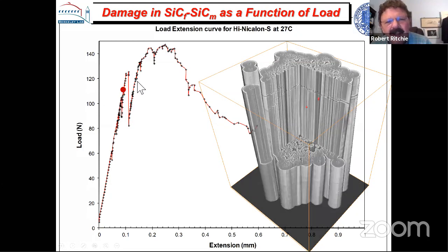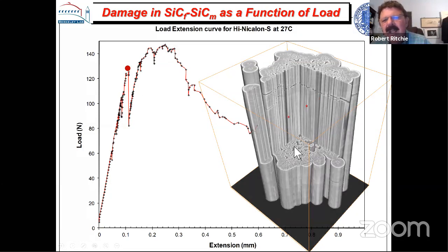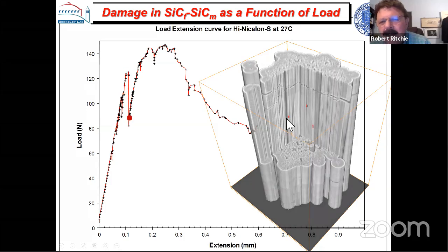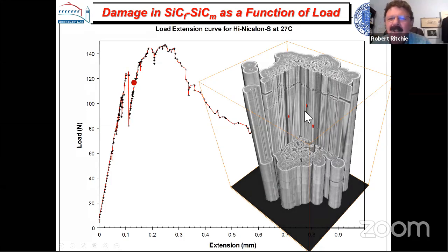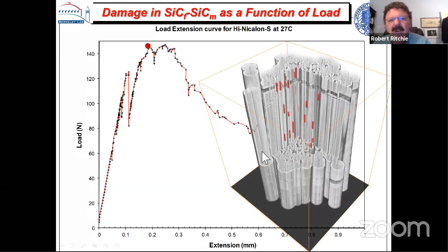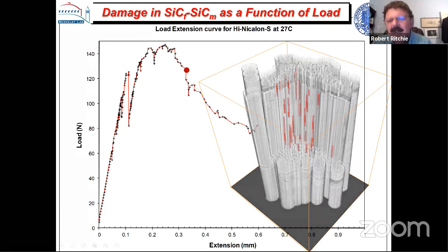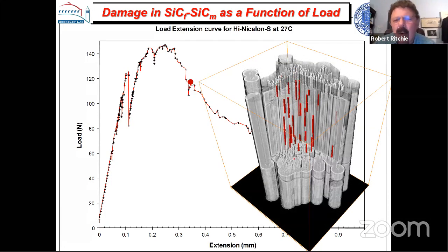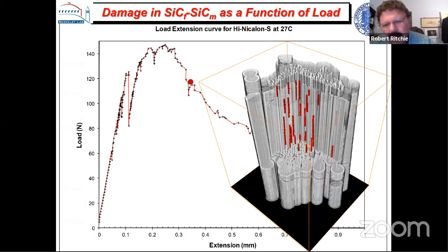But during the tensile test, we can see into the material. We can see how every fiber breaks. We can look at the distortion or the pull out, and we can see the bridging developing and the various different cracks as a function of load. Everything you see in that image, we can quantify with this technique. This was developed in a program with Brian Cox and David Marshall, and a lot of this was done by my postdoc, Ritchie.